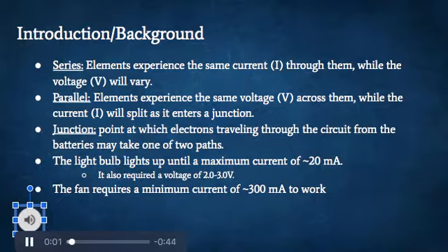We had to keep several circuit rules in mind when designing our circuit. There are two ways circuit elements can be arranged. The first is in series or in a loop. In series, elements will split voltage, but the current will stay the same. When elements are in parallel, however, a junction is formed that creates a second path for the current to travel along. Therefore, current varies in parallel resistors while voltage is held constant. It is important to note that current travels along the path of least resistance, so junctions with greater resistance overall will experience a smaller current.